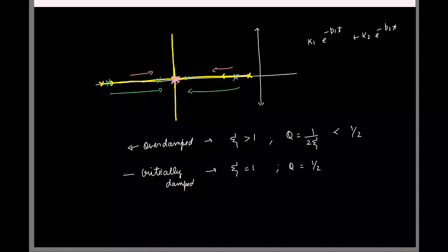Okay. And do you know what the corresponding phase margin is for this? Again, I'll give it as an exercise. It's a straightforward calculation. It turns out the phase margin for this is roughly 76 degrees. So if you can hit a phase margin of 76, it's very good. Else you try to keep it greater than 60 degrees at least. In fact, if the closed loop poles are lying on top of each other, the phase margin was 76 degrees, right? We saw that now.